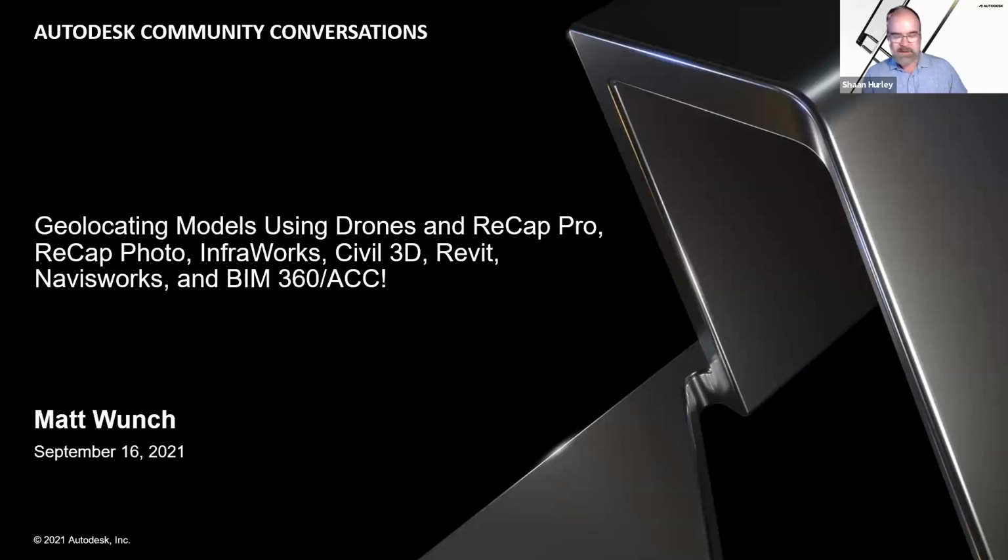So whatever your template is for surfaces, for alignments, for corridors, pipe networks, if that information resides in that InfraWorks model, it's going to be pulled across as these particular objects on your particular styles. So I'm just going to go with all objects, rather small area, and open model. And this should just take a moment or two to pull in this information.